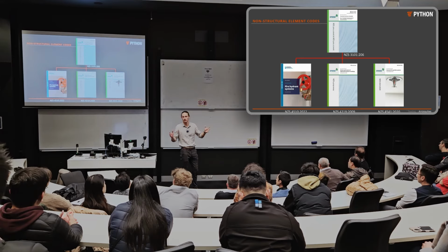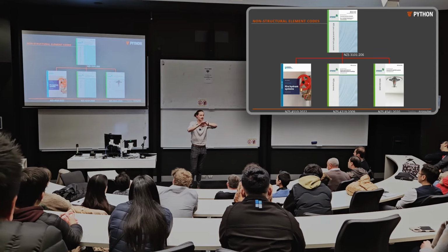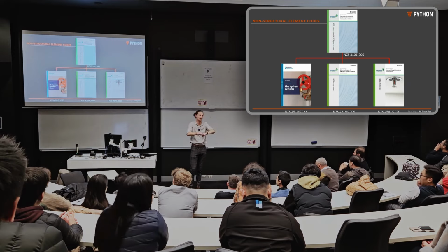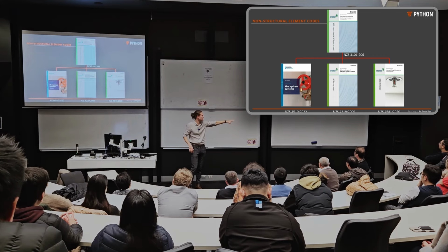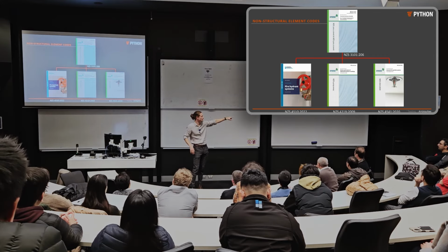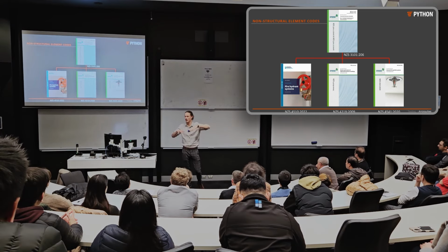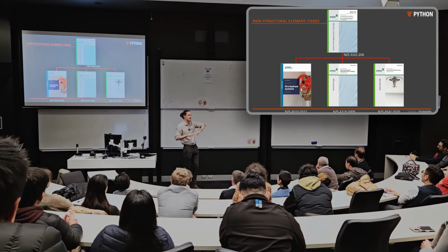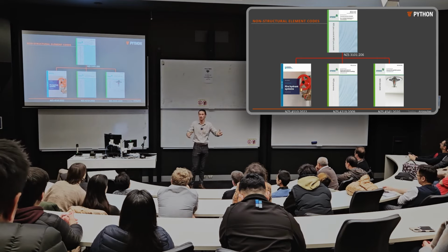Right? Fundamentally, our codes in New Zealand are built with a hierarchy. We have our Building Act, we have our building code, we have our standards. Our standards have a hierarchy. Right? We have loading standards, we have material standards, and then we have specific design standards. The ones at the bottom are all specific design standards. I think those specifically are fire hydrants, bracing, and automated sprinkler systems. Fundamentally, they are subservient to 3101. Right? 3101 requires use of a C2 capacity. Therefore, if you're following a specific design standard, that fundamentally still falls under the 3101 requirements.